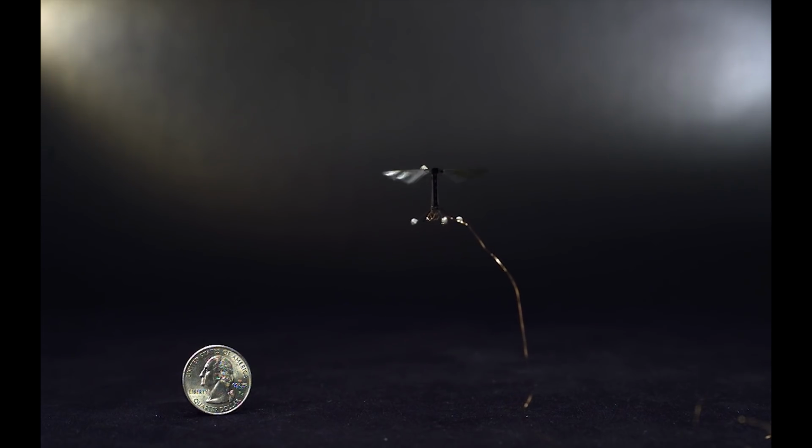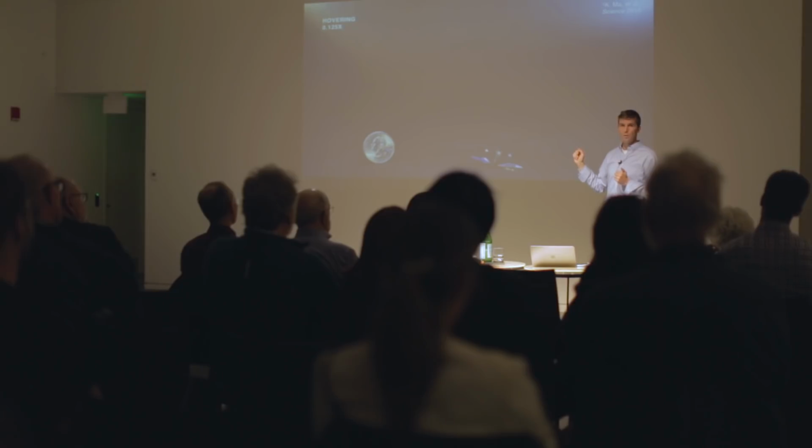Hovering is particularly challenging because, as I said before, in the absence of active control, this thing is just going to fly out of control. And in the absence of forward flight, there's no hope of passive stability here. So you really have to be active. That last half second actually illustrated one of the nice things about operating at these scales. You can crash these things all you want, and they're not going to break.